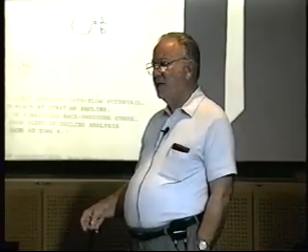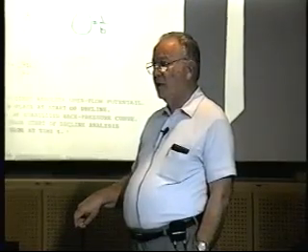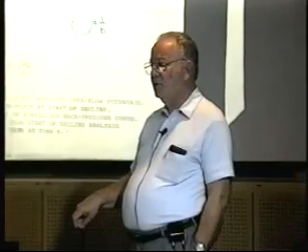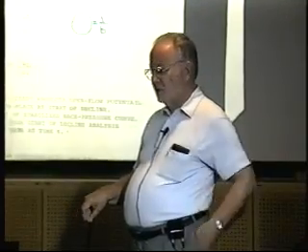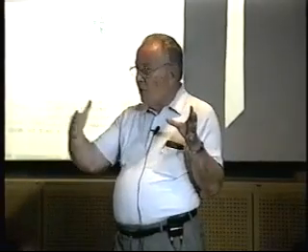There was a classic case run by Coats a long time ago on optimizing development of a field, and he had an example of a gas reservoir where he had a low permeability region and he had a higher permeability region, and the optimum way of developing the field was inverse to what everybody intuitively thought. You drill the low perm region first because you have to get that production on early as compared to the high perm, because you need as long a period of time as possible to recover that gas in the low perm region.